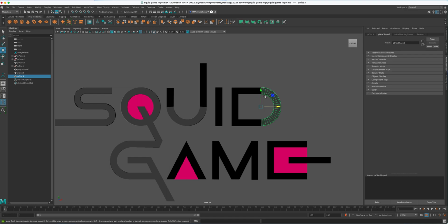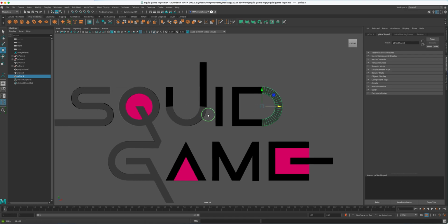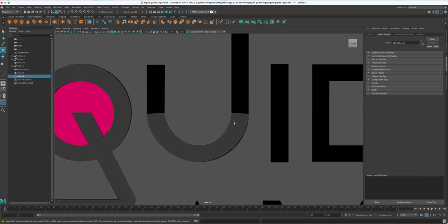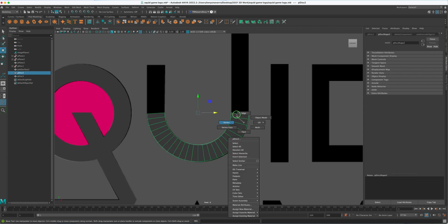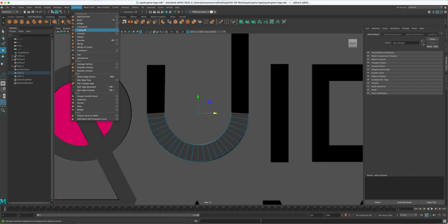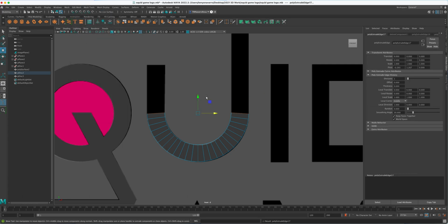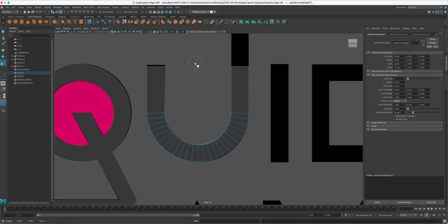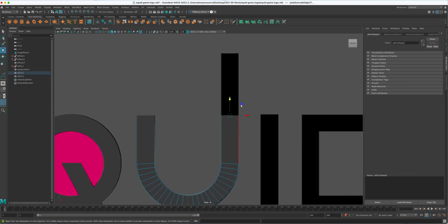Once we've done that, we have just some extruding to do. We have to straighten this out. Actually, we don't even have to. I'm fine with this. So I'm gonna take edge, shift click. Okay, let's not do the command, guys. We've been crashing on that. Edit mesh, and we're gonna go to extrude W and pull straight up. We're gonna press R to flatten that out, as you can see. Pull up. Now take this one and just push this all the way up.